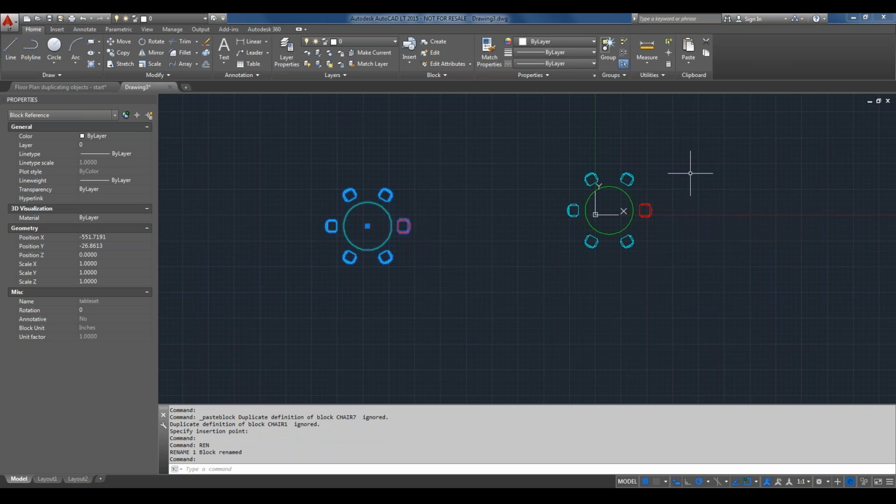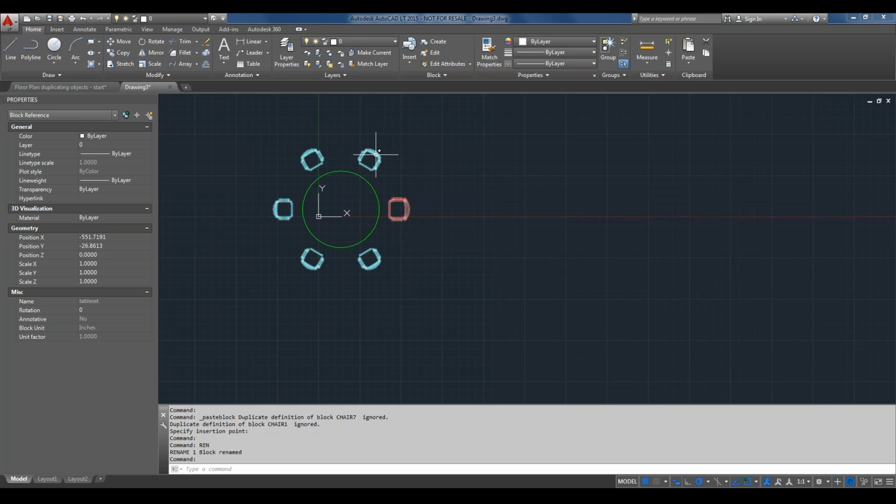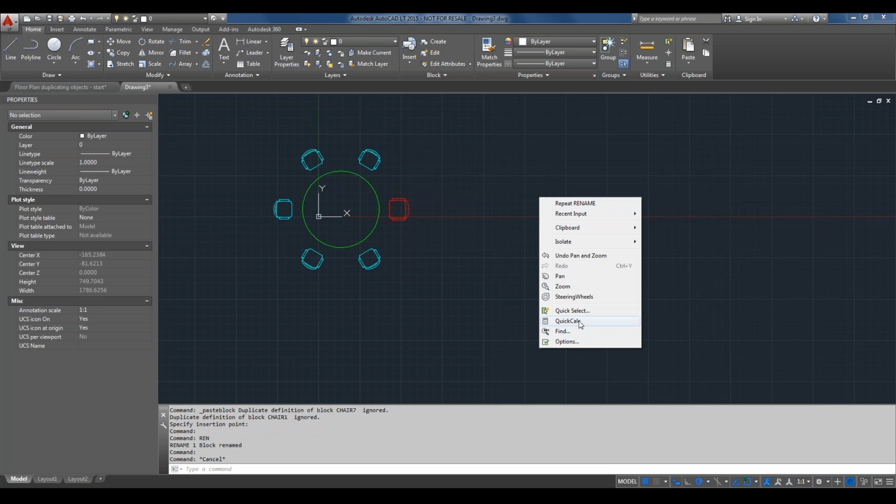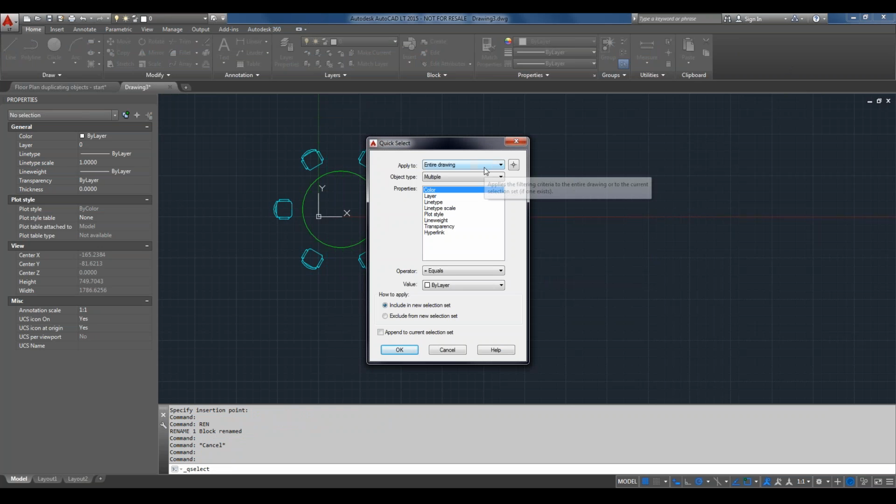While we have another minute or so, there's a few more questions too, so I don't know if we can squeeze those in before we end, if that's okay. Yeah, I was going to ad-lib. Let me see. So can you copy an entire layer to a new drawing, with objects on it, I'm assuming? I think you'd basically use quick select for something like that, wouldn't you? I would agree with that. You may have to bring the layer name in using Design Center. But yeah, quick select would allow me to select.